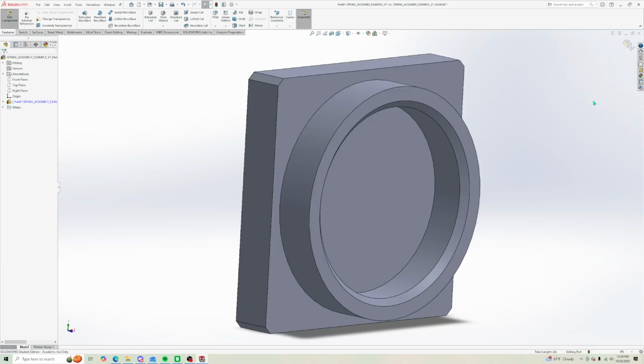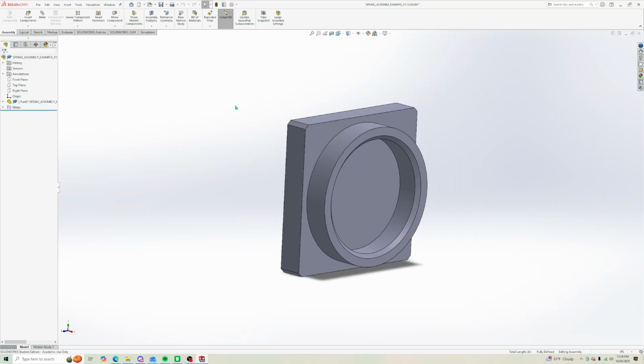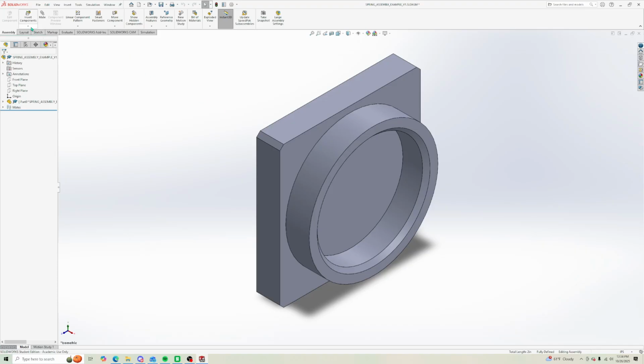So now we're on step 6, so exiting the edit component mode. So this is part of where I was messing up. Click the edit component command again to turn it off. The first component is no longer active. Its color changes back to default gray. So we're in edit component. We're going to hit off of it. Okay, you can hit Control 7, go back to isometric.